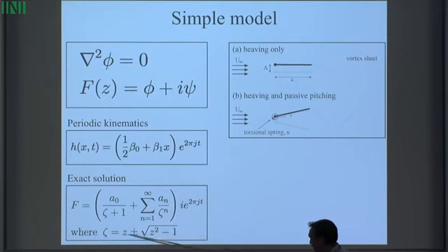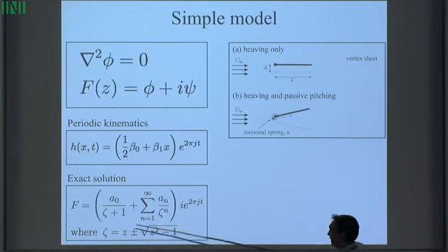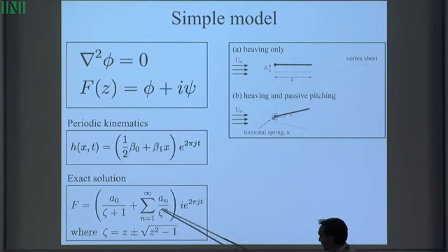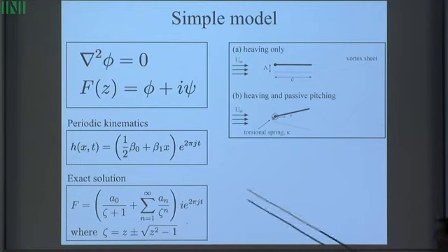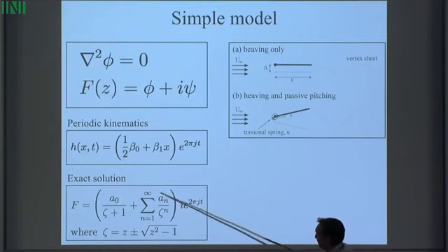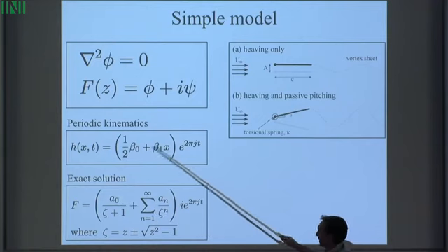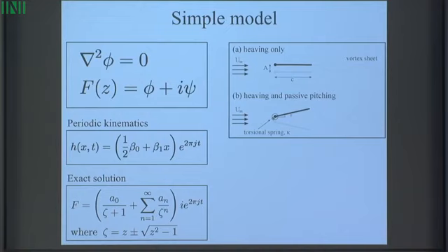You see a Joukowsky transform here, which maps the wing, which is a line segment, to the unit circle, and then perform this multipole expansion with a singularity at the leading edge and the rest centered at 0. And I could get all of these coefficients explicitly in terms of the known kinematics. And then I've solved for the flow field exactly.